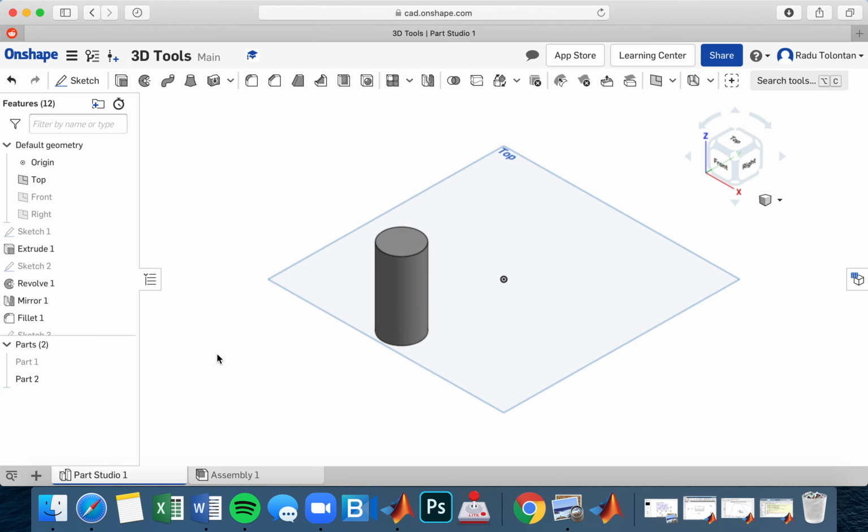Perfect. Now, I will show you how to create the exact same cylinder, but using the revolve pattern, because as you can see, cylinders are very circular. It is usually a great indicator that you're able to use the revolve efficiently if the part has a single axis of symmetry, which in the case of the cylinder is its center axis. Now, let me show the front plane, and let me move to the front plane to sketch something on it.